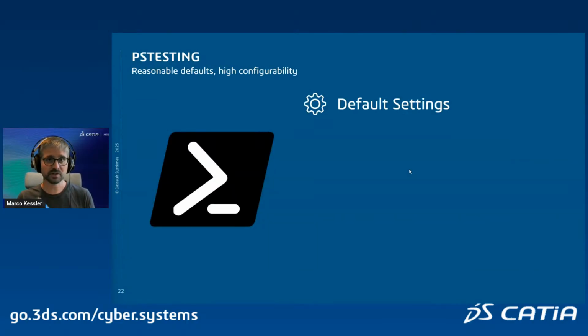So what we do is we run everything with a default settings file, which means we ignore the setup.mos file in your user folder. You can change that if you want, but this allows us to test everything in a neutral Dymola environment without any changes made by the user to the advanced flags, for example. Next is, as we don't use the default Dymola setup.mos file, we don't know which compiler to use because that's configured in this one. So we just detect the Visual Studio installations and use the latest compiler. If you don't want it, you can change that.